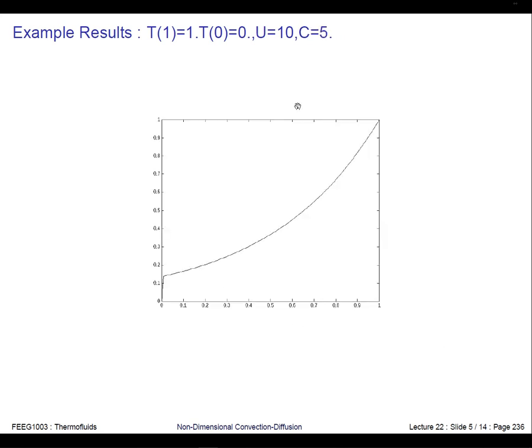And then the flip side is, if we take our velocity back down to 10, we make our diffusion coefficient 5 times bigger, we then see that it becomes very much a diffusion dominated problem. So there's a lot more hot fluid in this domain, and the convective flow can't really push the cold fluid into the domain here, and the convective and the diffusive power is such that we would call this a sort of diffusion dominated problem.